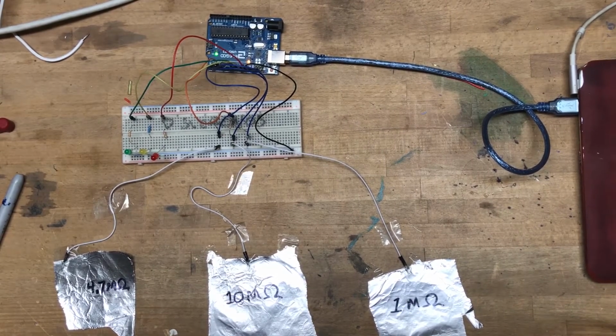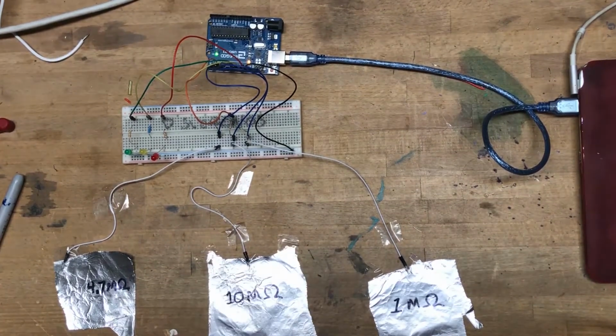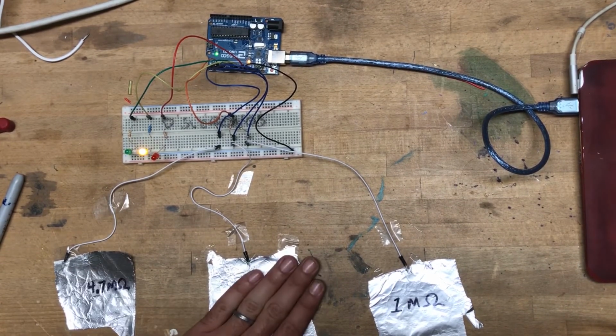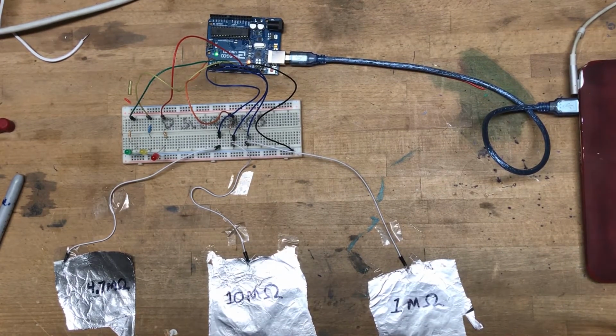So here's the circuit for our next switch operation. We're going to be working with capacitance switches. So these are switches you might have seen in like a lamp potentially, and we're basically going to be building this ourselves with the Arduino, some high ohm resistors, and anything conductive. In this case, I've got 3 different pieces of foil connected with jumper wires just taped on, just metal to metal connection, back to the board, and each one controls a different light based on the capacitance that the Arduino is sensing.